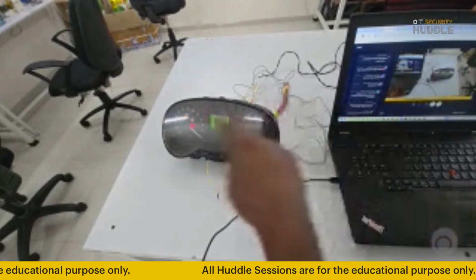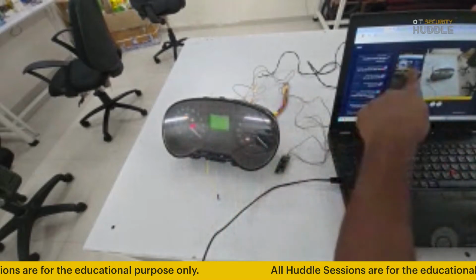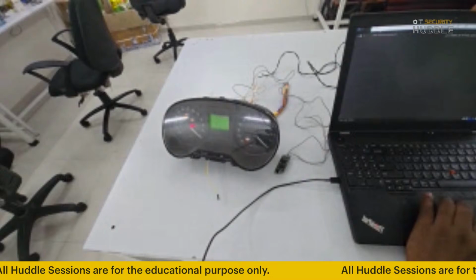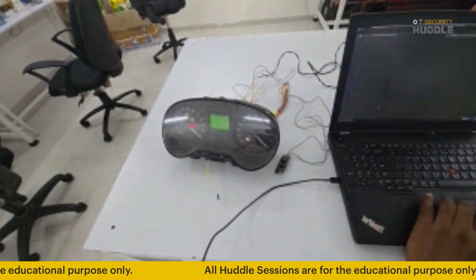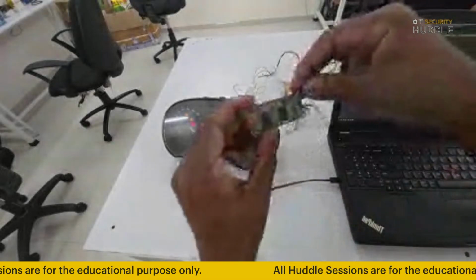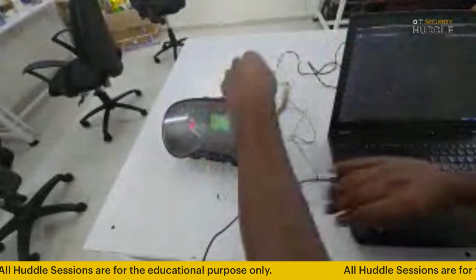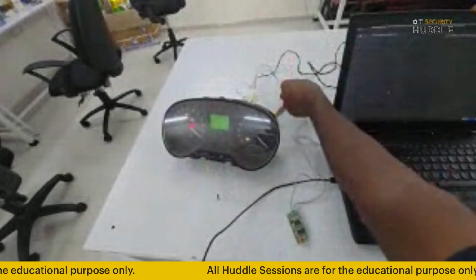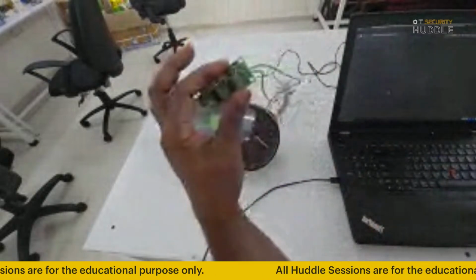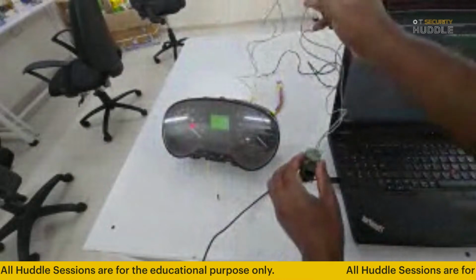Okay. So this is the cluster. You can see the commands here as well. So let me fire here. Okay. So we are going to use this tool, the USB tin. And we have the cluster over here. This is the harness. Harness is nothing but wires, and we identified the CAN high and CAN low wires. This tool has a CAN high and CAN low over here, and it is connected to the CAN high and CAN low wires as well.